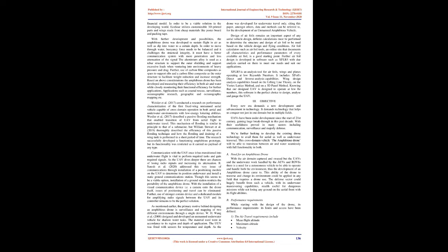Components and design of the amphibious vehicle are developed with due consideration for aerodynamic, structural, and environmental aspects. Starting with the payload and parameter calculations, the wing design and analysis are carried out in XFLR5 software. Finite element analysis, FEA, on static thrust conditions and skirt pressure are performed to evaluate the strength of the structure. For diverse wind conditions and angles of attack, AOA, computational fluid dynamic, CFD, analysis is carried out to assess the effect of drag and suitable design modification is suggested.